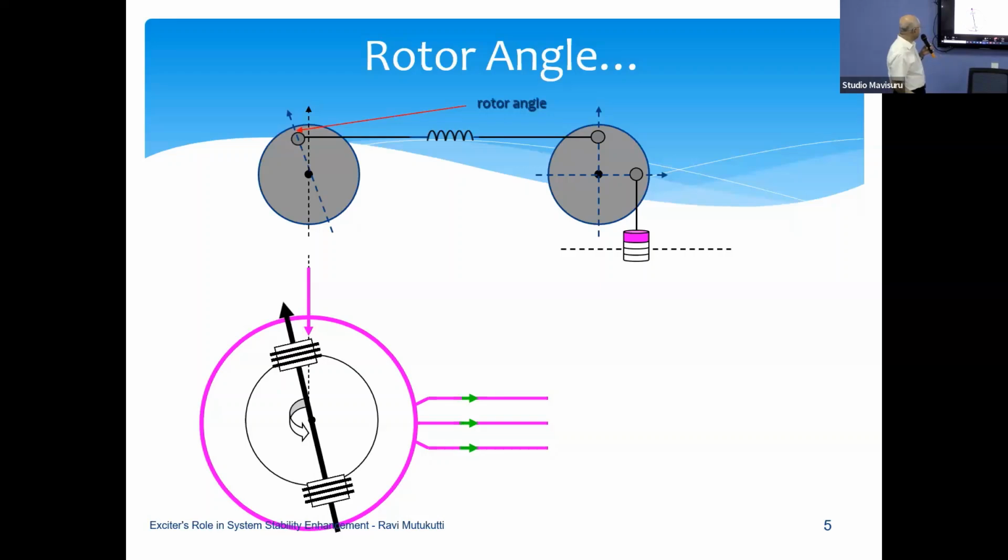Whenever you put more load, you have more current going on the stator. That current relationship needs to be maintained in force balance. So under the force balance, in order to balance that external force, you need to advance the rotor to a different place. So this angle between the stationary rotor field and stator field, we call it the power angle.